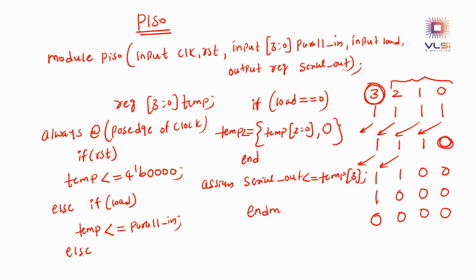While designing, you are using a mux. For the mux, you are giving a selection line like load by shift bar. Depending on the selection line, when load by shift bar equal to 1, it will do the load operation. When load by shift bar equal to 0, it will do the shift operation.